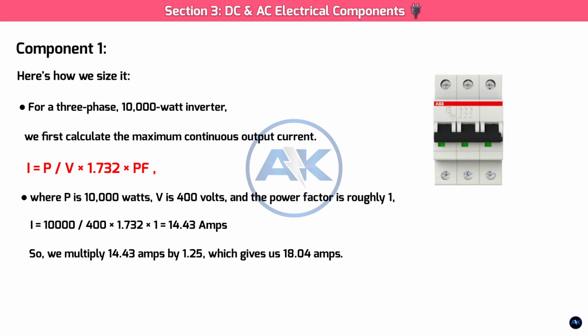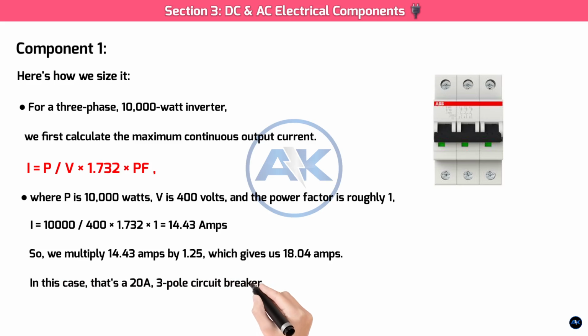Since breakers come in standard sizes, we always round up to the next available size. In this case, that's a 20 amp 3-pole circuit breaker. It's the perfect size to protect all 3 phases of your system.